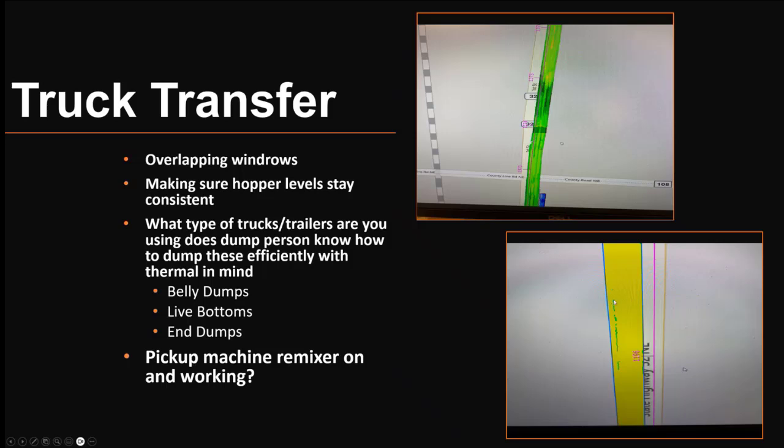Compared to this, you only have 10 degrees of variability here compared to the 30 here. You'll see a turn lane here. Typically, these came from a MnDOT project, and they really only require the mainline scanned with the technology. So when you go past that, the approach was paved with the paver, and you can see the colder asphalt there. It could have been paved hours ahead of time, so it definitely cools off.